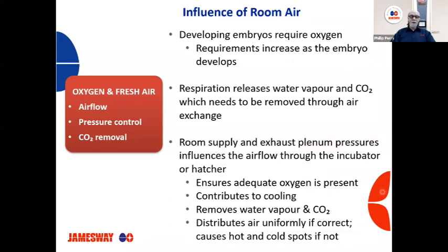The room supply and exhaust plenum pressures influence the airflow through the incubator or hatcher, which we touched on. It ensures that adequate oxygen is present, contributes to cooling, removes water vapor and CO2, and distributes the air uniformly if correct, and it causes hot and cold spots if not.